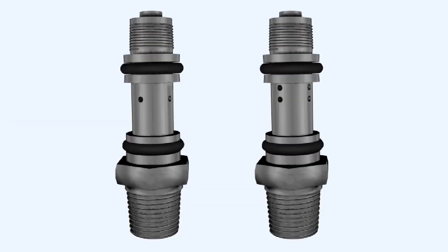A fuel discharge nozzle is located in each cylinder head, with its outlet directed into the inlet port. Nozzles are calibrated in several ranges, and for best results, in both economy and engine power, are fitted to individual engines as a set, each nozzle in a set being calibrated for its particular position on the engine.